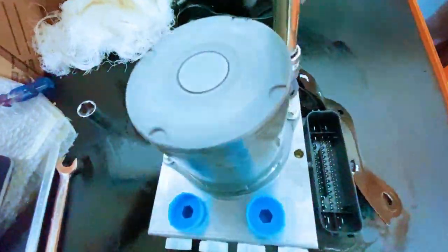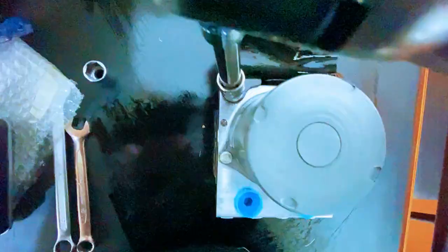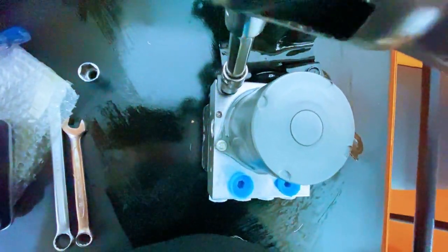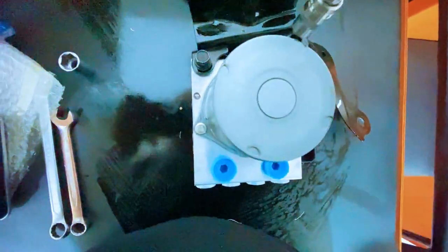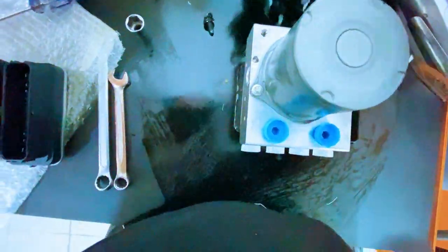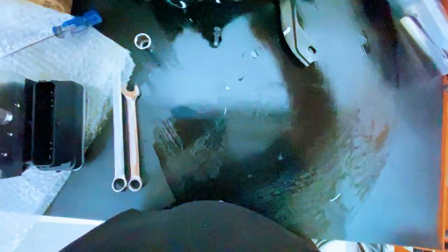C060962 and the EPB. Now let's talk about the third code, C060962. Toyota defines this code as electric parking brake switch signal compare failure. At first, this looks like a completely separate EPB problem. But this is where understanding the Toyota brake control system becomes important.